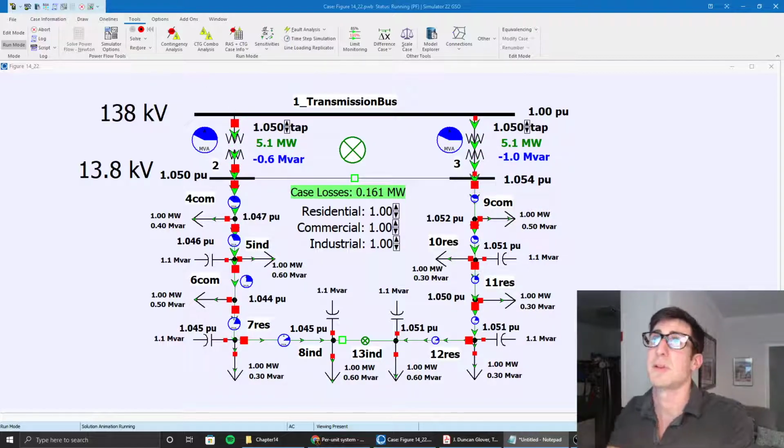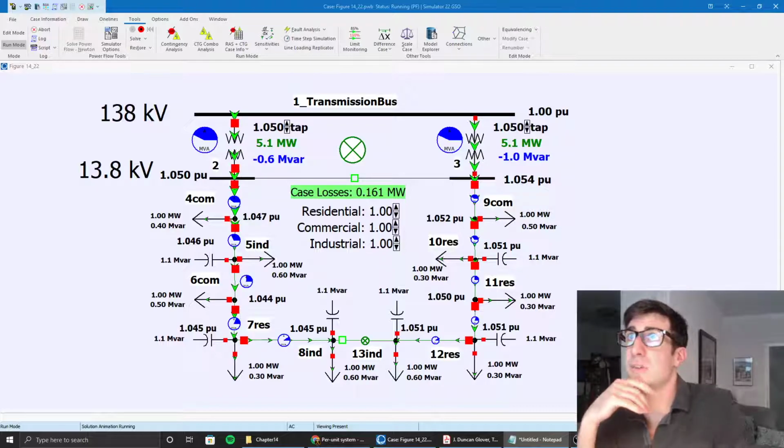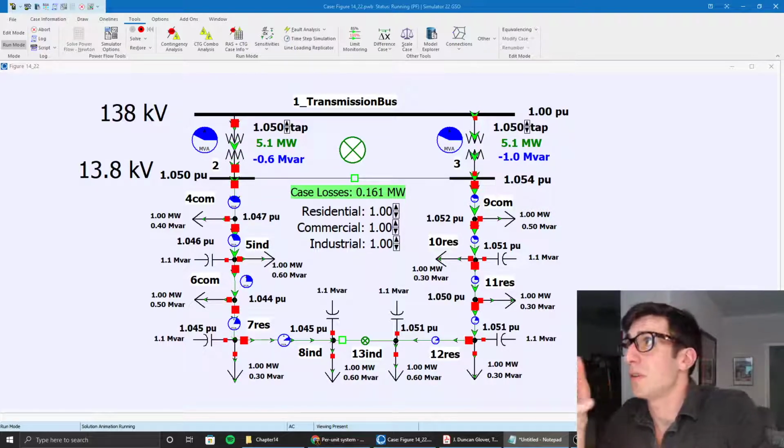So a few characteristics of a primary loop system is that they're very compatible with automation, and now that there is more monitoring and control thanks to the Internet of Things and low cost of computers, we're able to automate these systems more and isolate faults and sectionalize them. A loop system is pretty easy to imagine.